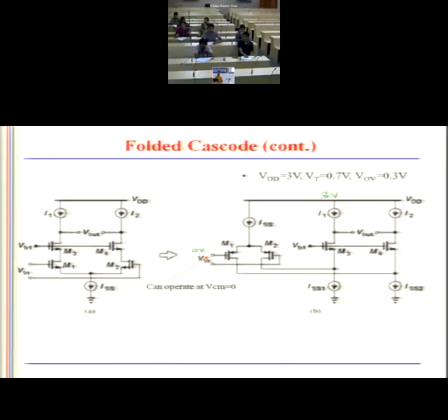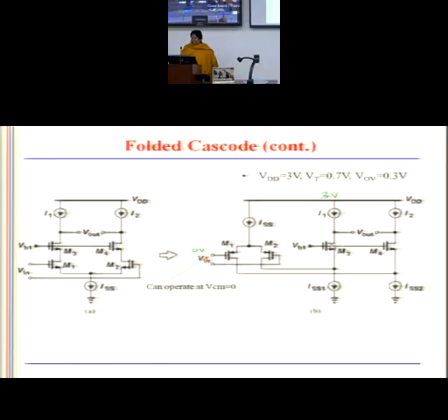ro1. So I do not want ro, because otherwise the high R out of this structure will have no meaning to me. It will go wasted. So I need to go and cascode over here. I need to do cascoding. So it should be a stack of 2 transistors here. So replace I1 by a stack of 2 transistors. Replace I2 by a stack of 2 transistors.